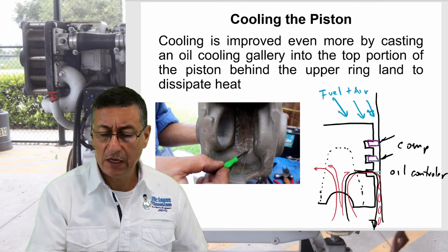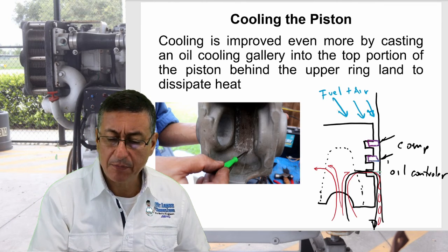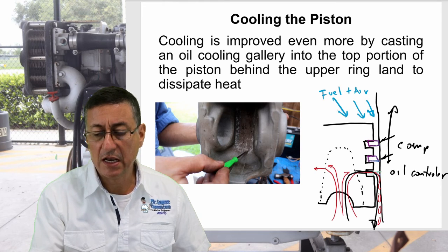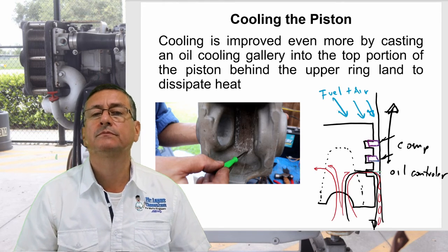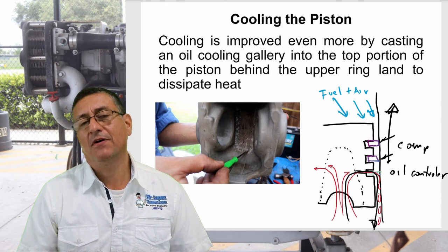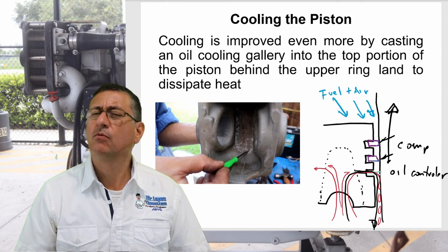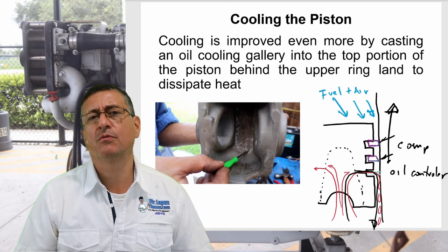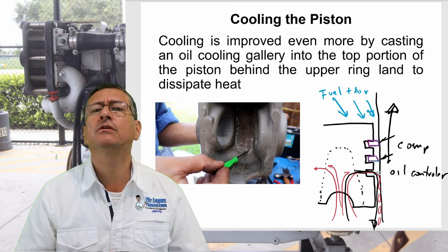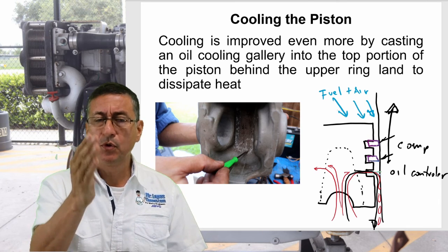We don't have oil going up from this point and up. In other words, if you have oil in the combustion chamber, what is the symptom? Oil entering the combustion chamber during the explosion. What is the symptom? Yes, blue smoke.